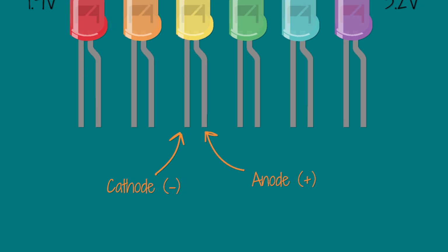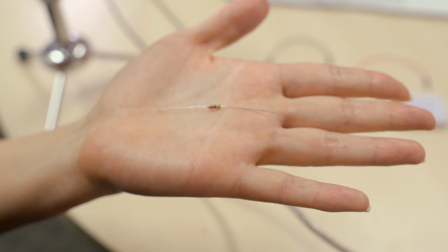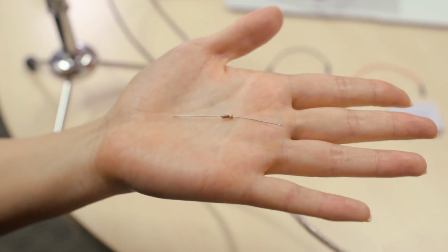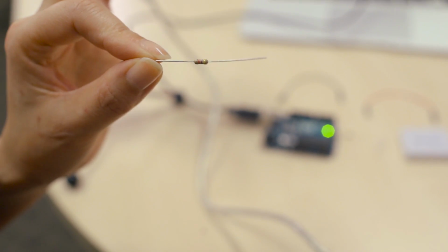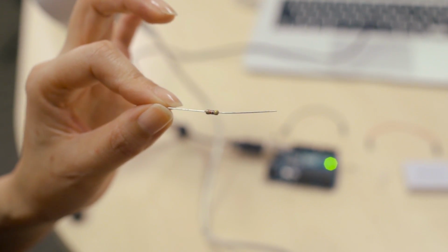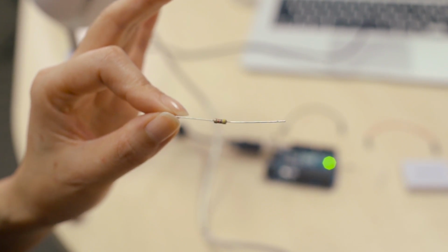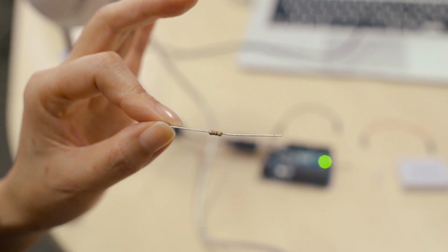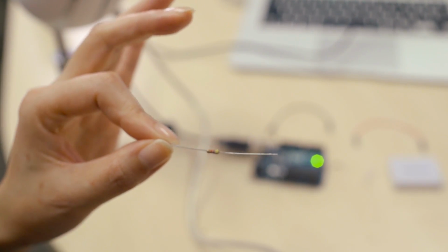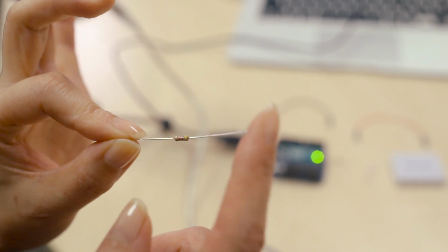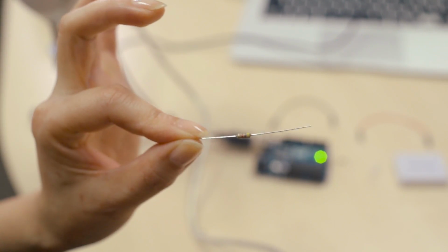This little funky looking thing is called a resistor. It has wires sticking out of each end with some 4 or 5 color bands. In an electronic circuit, resistors are used to limit the current flow. If you supply too much voltage, an LED can't pass so much current, so you will burn the LED. So you have to use the right resistance.